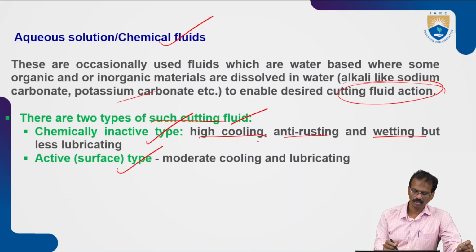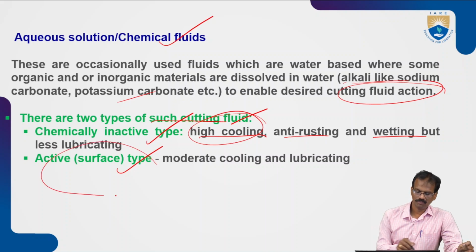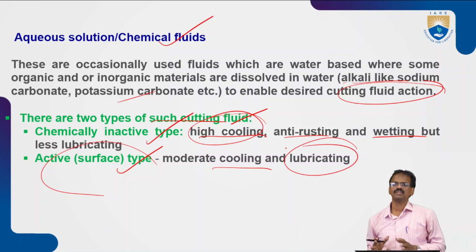So, for a requirement of high cooling and anti-rusting, we can prefer the chemically inactive type. For chemically active type, there is moderate cooling and lubricating purposes. So based upon our primary requirement, you can use this type of cutting fluids.